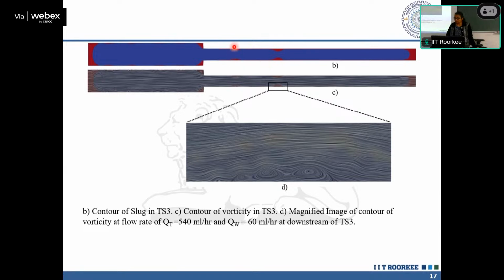This disturbance wave, which results from the sudden abrupt change in the flow path, is actually enhancing the mass transfer in the downstream. Otherwise it is the 2 mm, isn't it? And the 2 mm straight gives us the lowest efficiency. It is due to this phenomenon that the mass transfer efficiency of such geometries is higher.